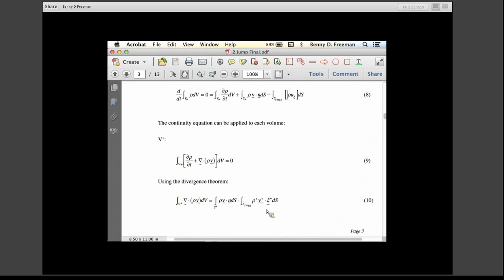Now, it turns out, and we'll see this in just a moment, that because V plus, at least all parts of it that are on S plus, is a material volume, there'll be no net mass transport coming across that material volume. That's the definition of a material volume. But you can certainly have material enter and leave V plus across that phase interface. And that's what this term represents. This is the density, if you will. If we use the plus phase as a gas phase, it's the density of the gas phase times the velocity of the gas in the direction into the material volume, V plus.